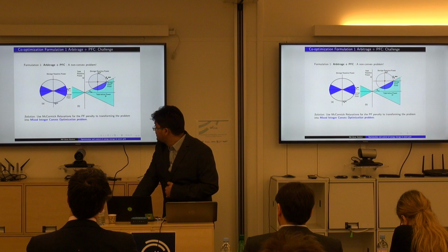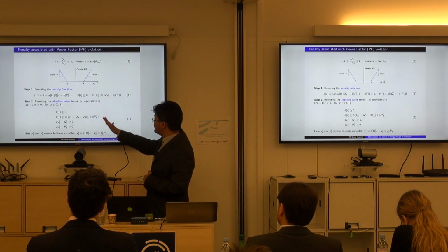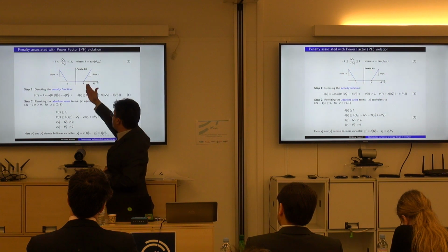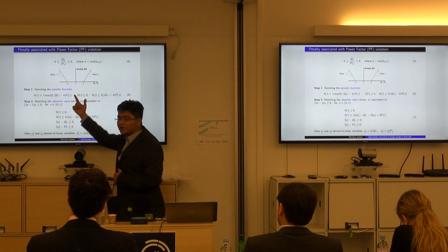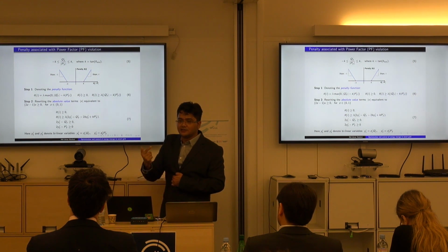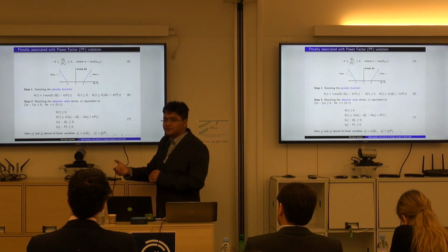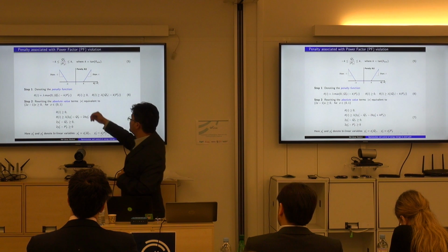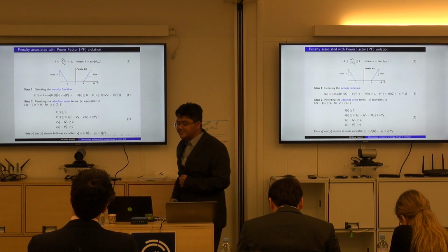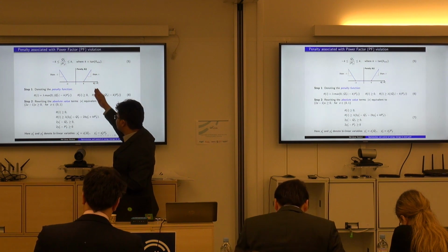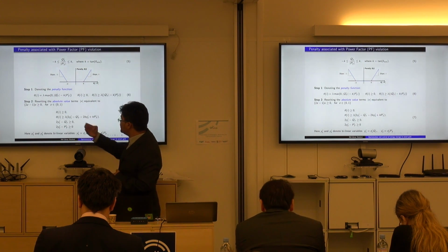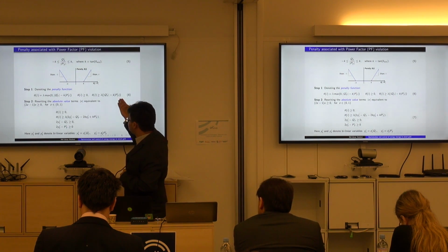In this co-optimization setting, we are using a penalty function which penalizes the power factor. Whenever the power factor is leading or lagging beyond a certain level, in this case beyond k and minus k, it is penalized. This is not actually the power factor, cos of theta, but tan of theta. We take tan because it simplifies and linearizes. It has a piecewise linear structure, and we can denote this cost function in terms of a max function. Only when the power factor is beyond a certain level is it active, otherwise it is not. We can denote this as two sub-constraints.